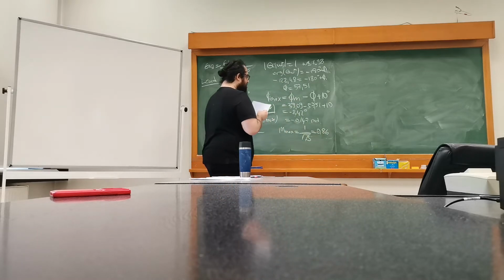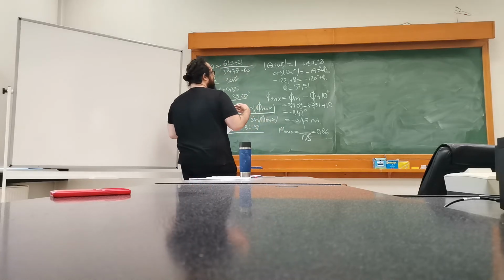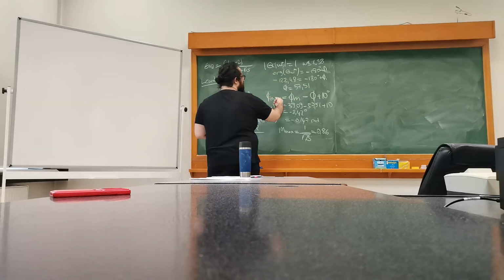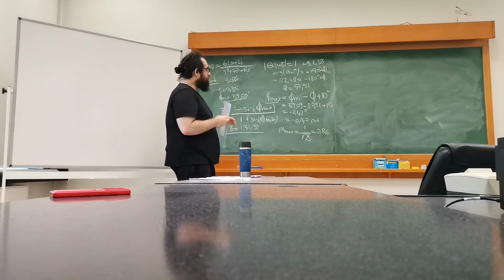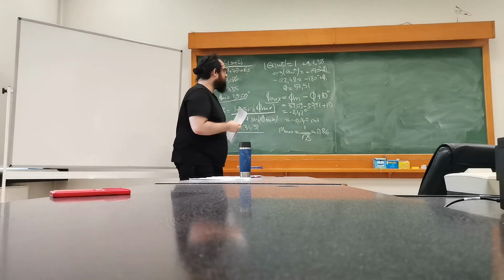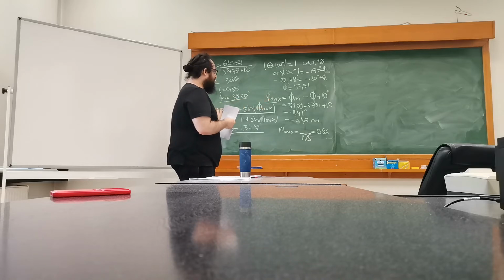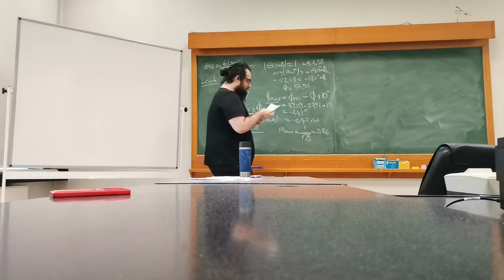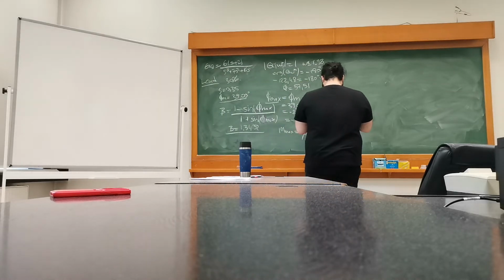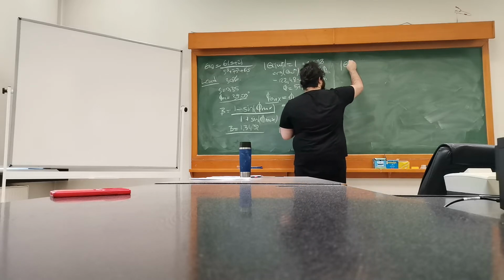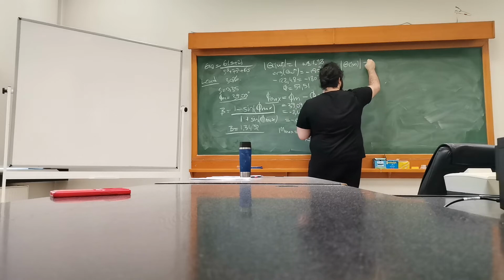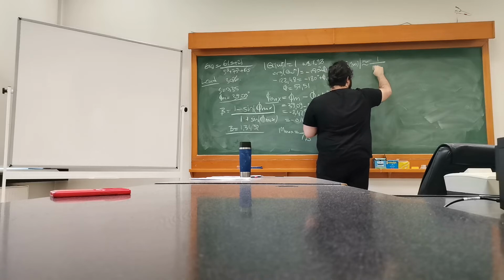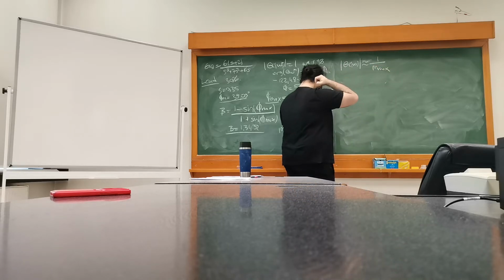Up to this point, we have done the following. We have looked at the system's phase margin, the desired phase margin, and shown the maximum phase value accordingly with a 10 degrees increment. Then we've used that phi max to come up with a beta value, which is one of the controller parameters. Then we get a maximum magnitude. This magnitude is important because we are going to search for it. So we're looking for the frequency where we have approximately this. So this point needs to be searched.